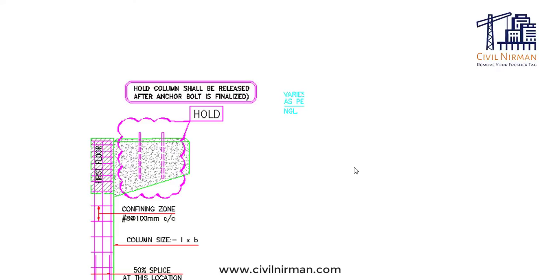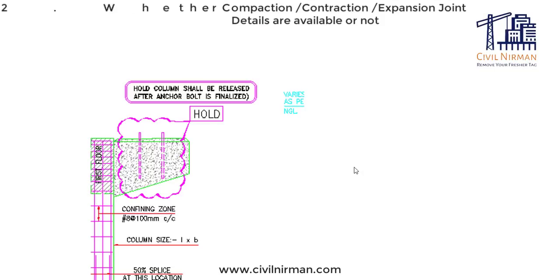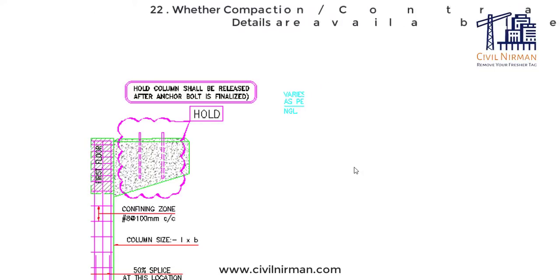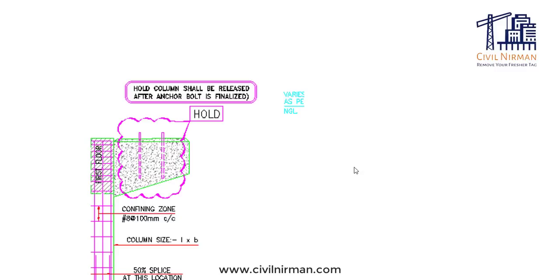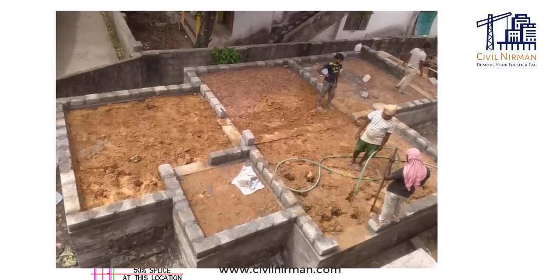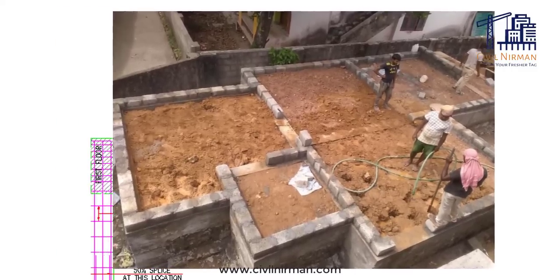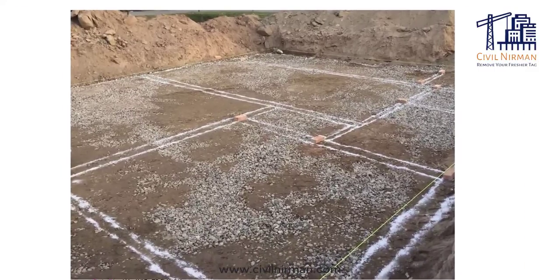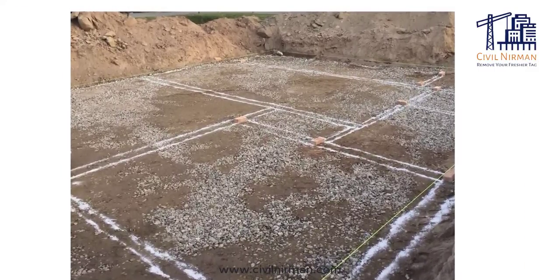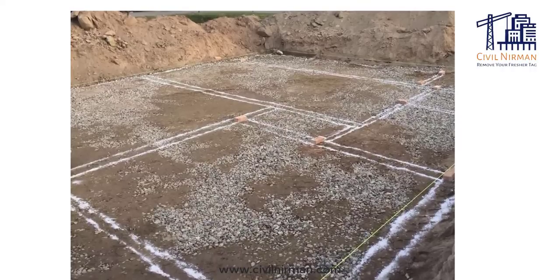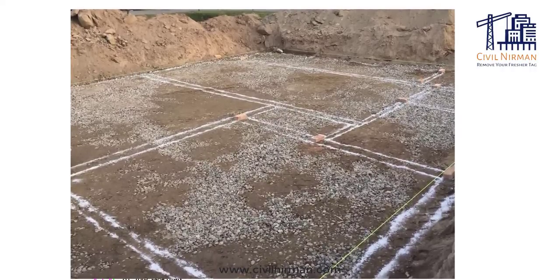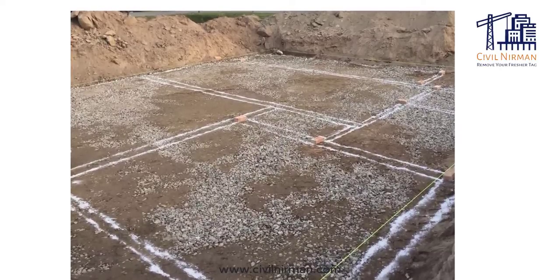Then the final tip related to the typical compaction, right? You need to make sure whether the backfilling is to be done with the existing excavated soil or not. Confirm this with the BOQ, or you can ask your project coordinator if it's not available. And if the backfilling is to be done with the available earth, then remember that the compaction is done in layers not more than 300 mm each to achieve 95% maximum dry density. Okay, so you need to provide the compaction detail as well, right?